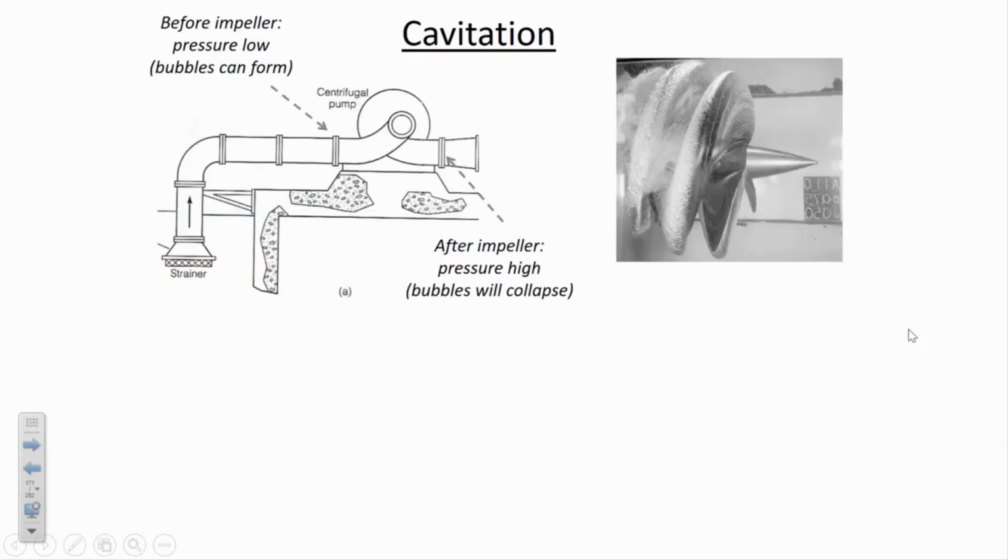All right. So here's that diagram that we looked at previously on Monday when we were discussing pumps. The issue with these pumps is that on the suction side of the pipe, the pressure is going below atmospheric pressure. In absolute terms, our standard pressure is 101,325 pascals, and that's the pressure of the water where the air and the water are in contact with each other. Of course, if we go down through the water, the pressure is increasing, but when we go up through the water, the pressure is decreasing.